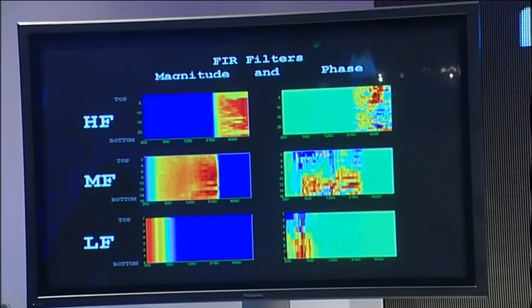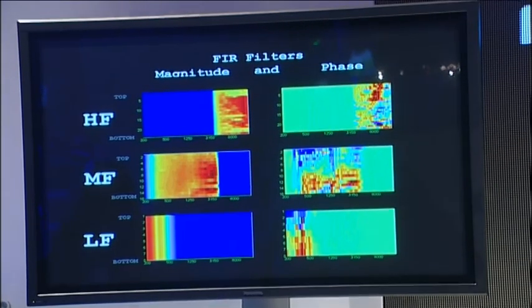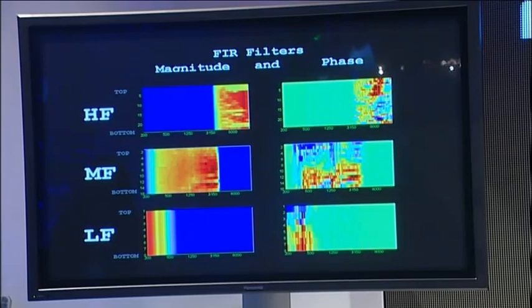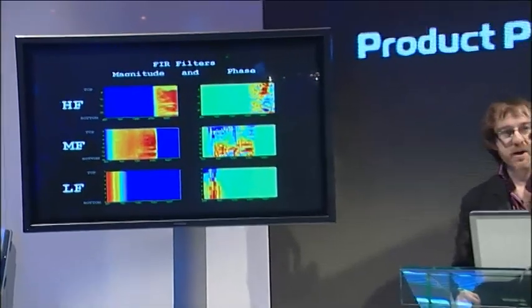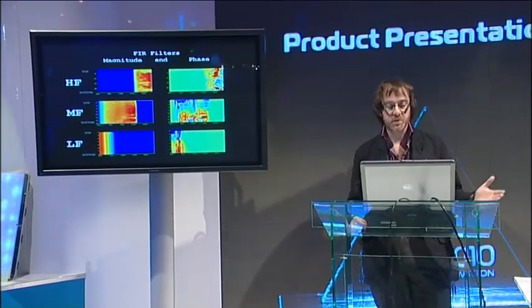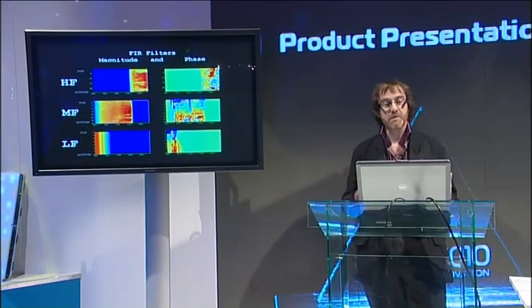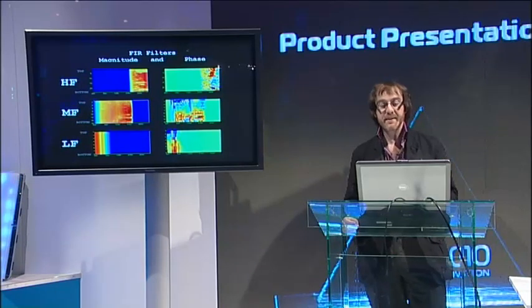And in order to do that, we've had to generate probably the most accurate model of array behavior in the industry to date. So we can predict from measured to predicted within plus or minus 1 dB variation. We did an AES paper about 2 years ago which actually proved that we can achieve that. So within each MLA we've got these 6 channels of DSP, and in order to generate these amazingly consistent frequency responses and SPL variations from the front to the back of the system, we're using FIR filtering. And that's because what we need to do is manipulate the magnitude and the phase of the signal to each individual cell independently.